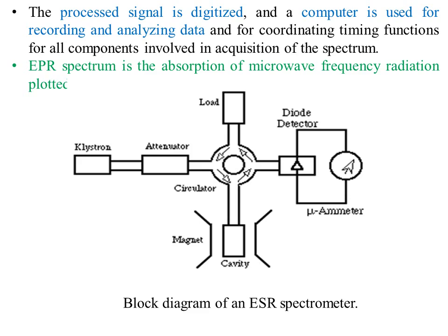So the microwaves are absorbed in the cavity, and the remaining microwaves go back towards the circulator, which resembles a traffic signal, and from this circulator they go towards the right hand side, in which you can see a diode detector which is presented like a triangle fixed in a rectangular box. So this is a diode detector which produces a signal.